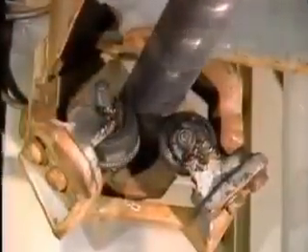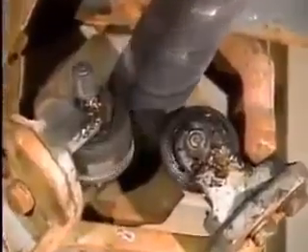The rollers support a device that's used to clean the tubes inside an operating boiler. Heat from the boiler is transmitted to the rollers and the grease. Grease made with ordinary thickeners would melt and drip out of the bearings, but the bentonite resists high temperatures, so it keeps the grease from melting.